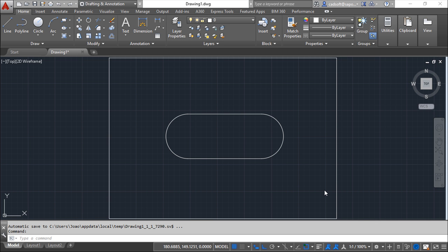For your understanding, you know that at the heart of these AutoCAD parametric tools are these dimensional constraints. Together with the geometrical constraints, they are the core of these functionalities. These constraints allow you to set and adjust the dimension of an assembly of parts, for example, or a single part. Thereby, this will give you an easy way to adjust the size and the shape of the assembly or of individual objects.